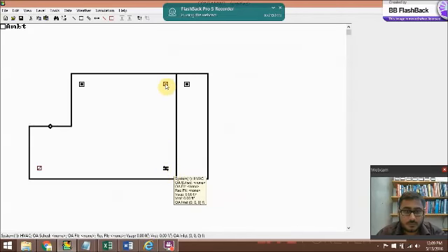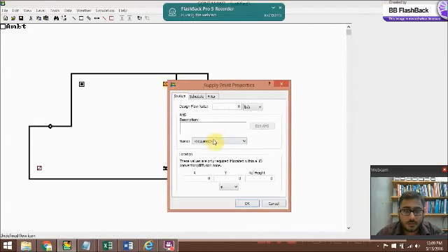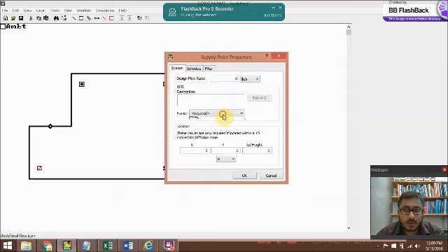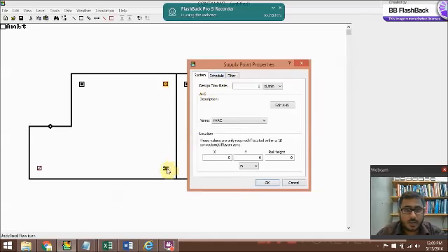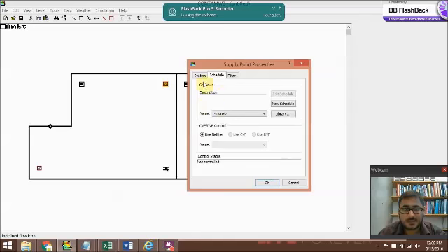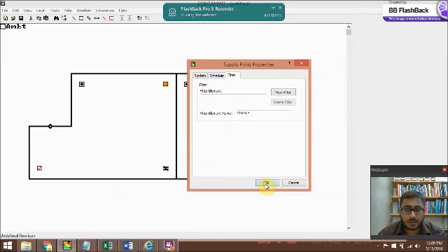So once your system name is set up, you'd have to go to the supply, select the system from here. This is your design flow rate. So in the main HVAC, we determine how much is your outdoor air. Over here, how much is your CFM for supply, and similarly for schedules or filter if you have any in the supply.